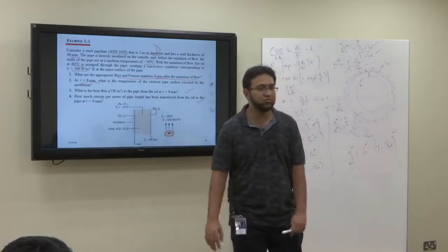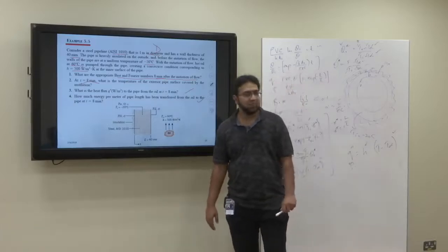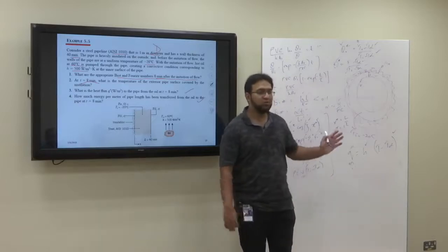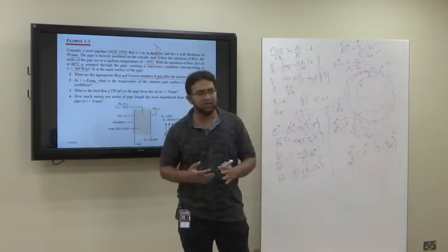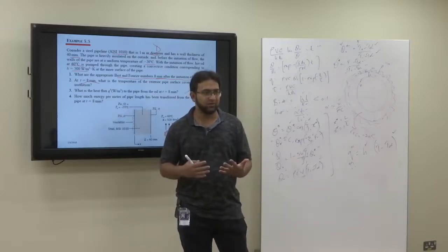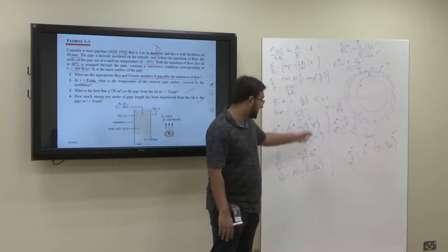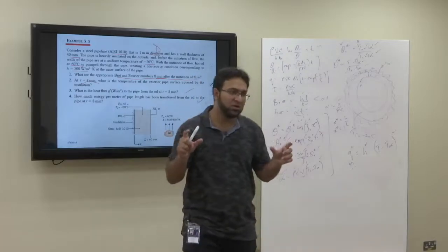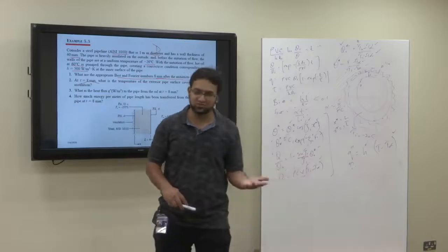Is there anything that you do not understand in the solution of the problem? The problem uses these formulas. These formulas are for the plane wall only, for the case where we have temperature gradients within the body and lumped capacitance cannot be applied. That was the case of the pipe, but we considered the pipe as a plane wall. By using the approximation of the plane wall, we solved for the case of the pipe.